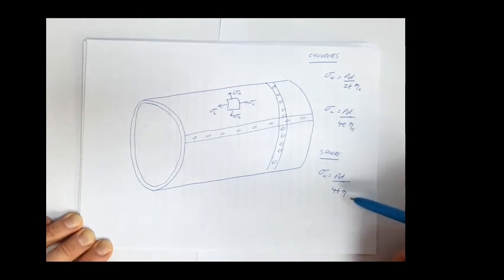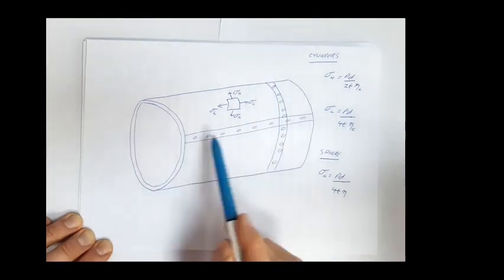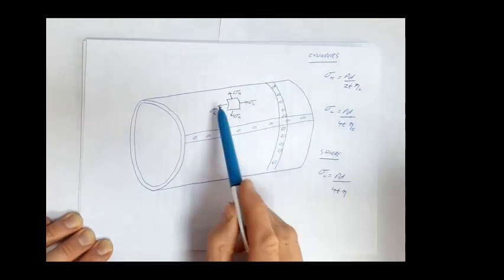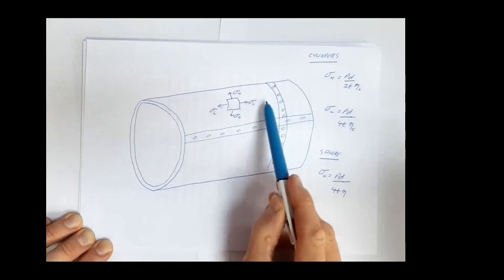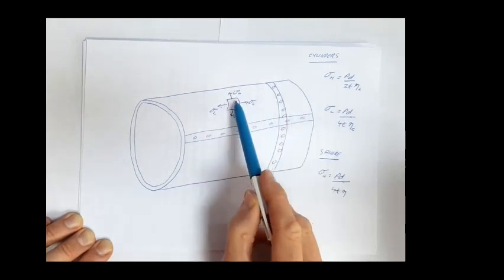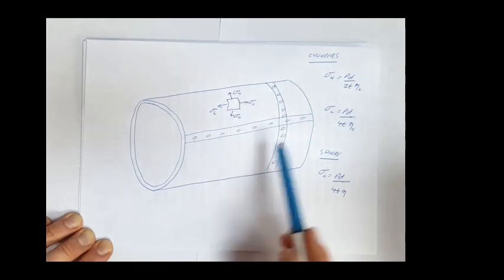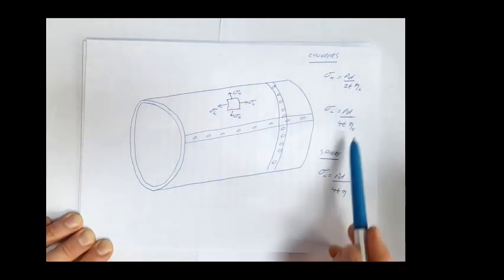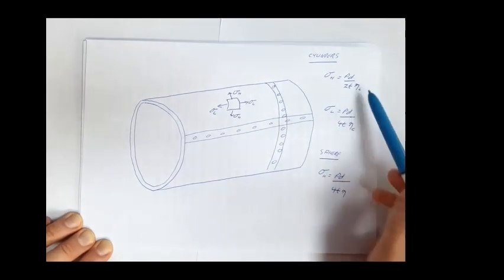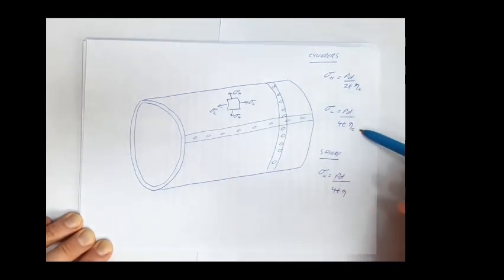So there's our structure, there's our manufacturing of our structure. Our longitudinal stresses go over the circumferential joint. The hoop stresses go over the longitudinal joint. And we just take those nominal stresses and we add an efficiency factor, either a longitudinal joint, circumferential joint, or if it's a sphere, the joint. And as I say, those values will either be established empirically through testing and experience, or through computational tools, through simulation and finite element analysis.